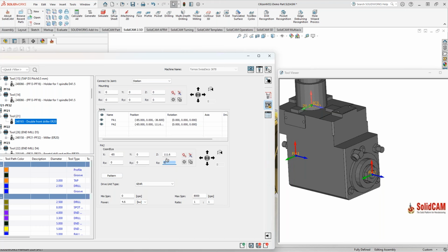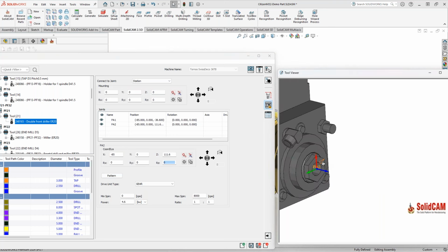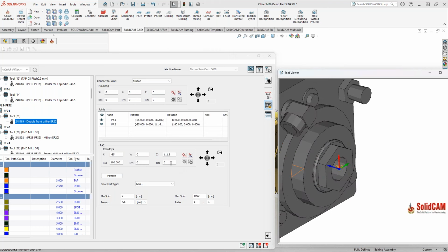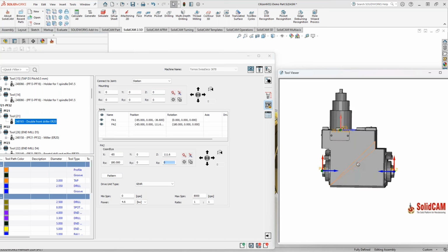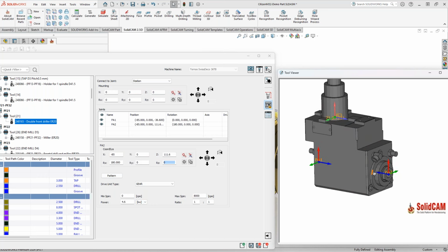So I'm interested in my Z vector to change it. If I click on this, I'm going to click on normal to this, and it's going to flip it. So pay attention, if I'm going to repeat the same process and click on the same normal, we're going to invert our Z axis. So I want to do it again. And now this is a proper orientation and location of my joints that I wanted to define.